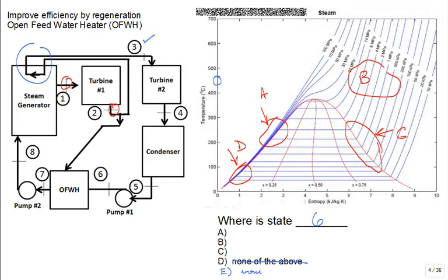Engineers try to minimize that pressure loss by giving it sufficient diameter in the pipe and sufficient area to go through that heat exchanger. But you're absolutely right. In reality, there's a small pressure loss, in any length of pipe. But hopefully it's small compared to the pressure gains for the pumps and the pressure drops across the turbines. Those are the two devices where we have our big pressure changes.